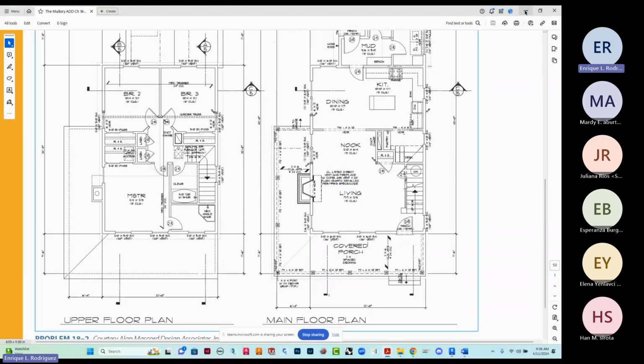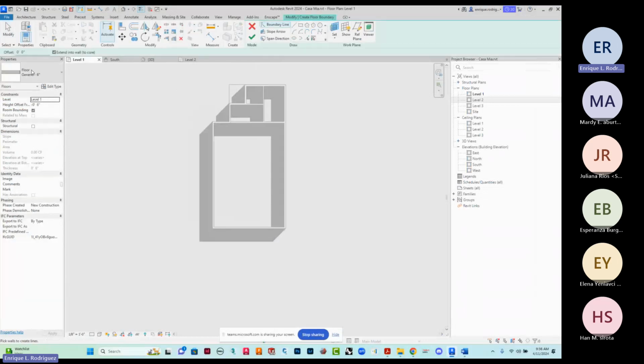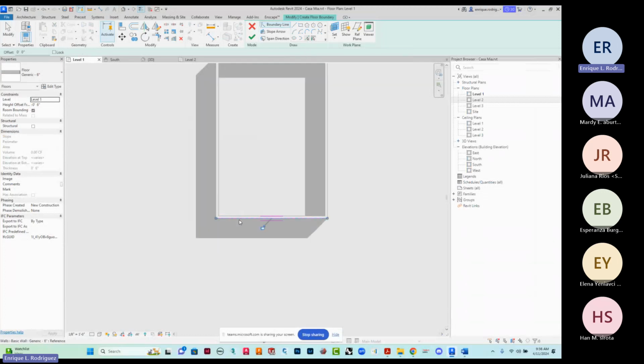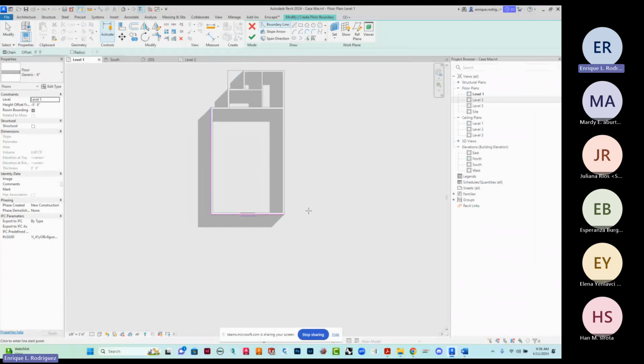All right, so let's go ahead. I'm going to minimize this, and I'm going to start to draw my porch. In this case, I'm going to go to the architecture tab, go to floors. I'm going to use the same one I used for the porch in the back, floor architectural. Defaults back to my generic 6-inch. But this time I'm going to start by using pick lines. I'm going to pick this line and this line. But then I'm going to switch to line work.